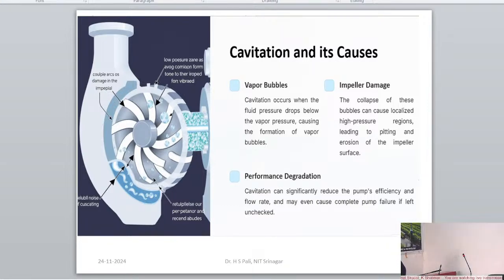Impeller size is another important part. If you want to increase the flow rate from the same pump, that is the important concept. We can change the impeller and change the flow rate. Here are the performance details of the pump with different diameter impellers. For example, 30 gallons per minute for a 4.5-inch impeller gives us around 13 feet of head.